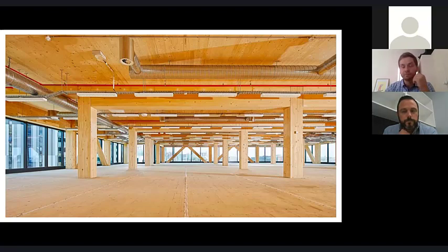But for a hotel style building, maybe you're going to have to take the International House approach with penetrations in beams and things, which adds a lot of cost. So look, it's about starting to think a bit differently, and your floor to floor heights is really important. Generally with these hotels, they're quite tight, about squeezing as many rooms on. The commercial offices tend to be a bit higher. So all of these need to be considered, and this is where the architectural view on it is really important. But I still strongly believe that there is a solution in there when you're combining all of them, and something that should be considered. Yeah, for sure.